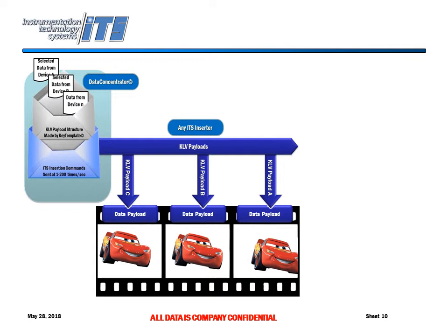We know of some others that will put the timestamp, for example, not on the first line, but actually when the vertical sync, as SMPTE defines it, is displayed, decoded. The problem with that is that the number of lines at the bottom of a video frame is a variable depending on whether it's a 720, a 1080, or even a 4K frame.